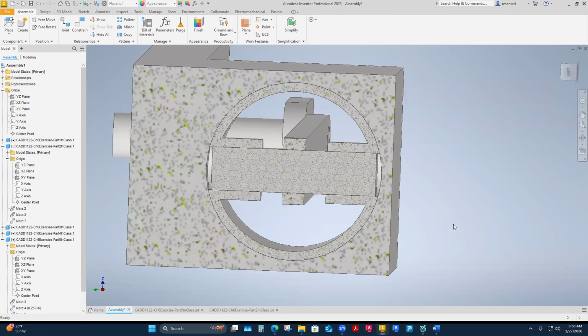So just always pause for a minute and be like, should this be a dimension or should this be a geometric? If you just cause yourself to pause, it's going to take a little while to build that, but eventually you'll learn that you're going to be putting more geometric type constraints, whether it's in your sketching in the part or even in the constraining in assembly.